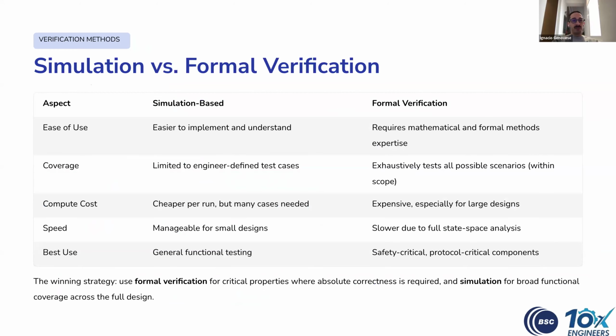Here we can compare simulation versus formal. Simulation is easier to implement and to understand than formal, and formal requires mathematical and formal methods expertise. Regarding coverage, simulation is limited to test cases, while formal exhaustively tests all possible scenarios within the scope. Regarding the compute cost, simulation is cheaper per run, but we might need many test cases.